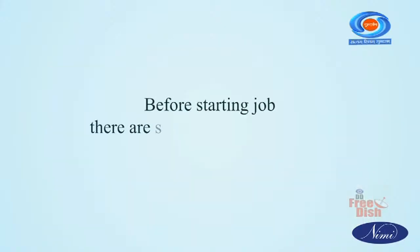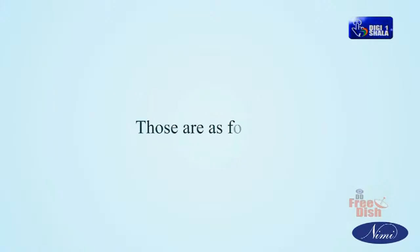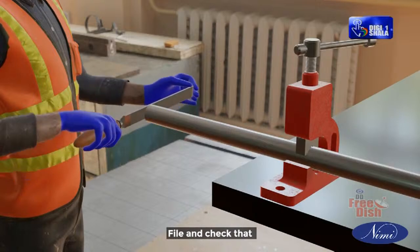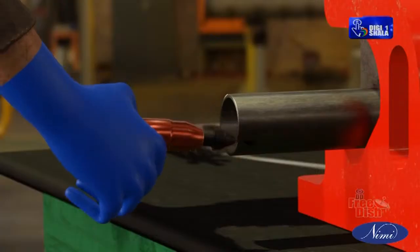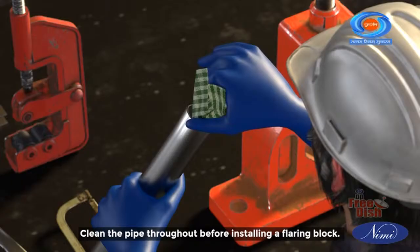Before starting the job, there are some preliminary checks to be made. Those are as follows. Check the material size and its condition. File and check that the end of the pipe must be exactly perpendicular to the pipe axis. Slightly deburr the inside and outside edge of the pipe. Clean the pipe throughout before installing it in the flaring block.